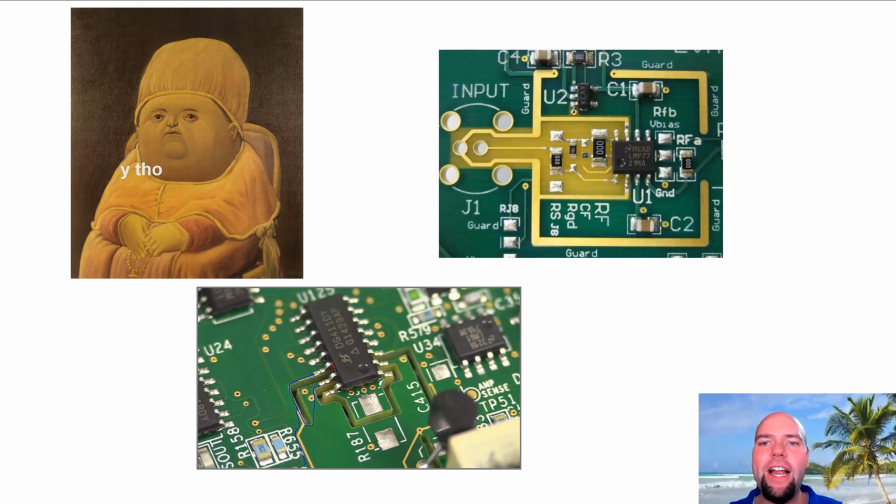There are a couple of ways to clean that up. You'll notice in this circuit, this is called a guard ring, but inside the guard ring, the circuitry, there's no green, whereas there's all this green here. That's because when they built this PCB, they specifically built it without solder mask.